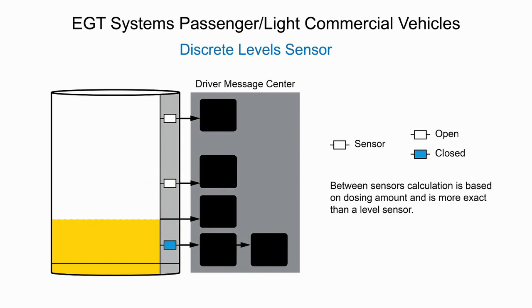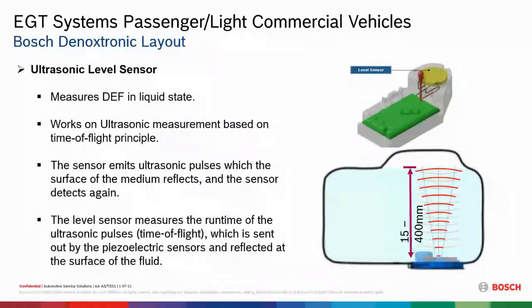Pretty much most manufacturers have gotten away from these now. Most of them have veered off to the next sensor I'm going to talk about in a moment. I'll let this finish its ride through here, let you see how it works. All right, and then we're down to a no start. That's going to be real interesting on the side of the highway if you don't keep your DEF fluid full. Make sure you keep some with you at all times if you can.